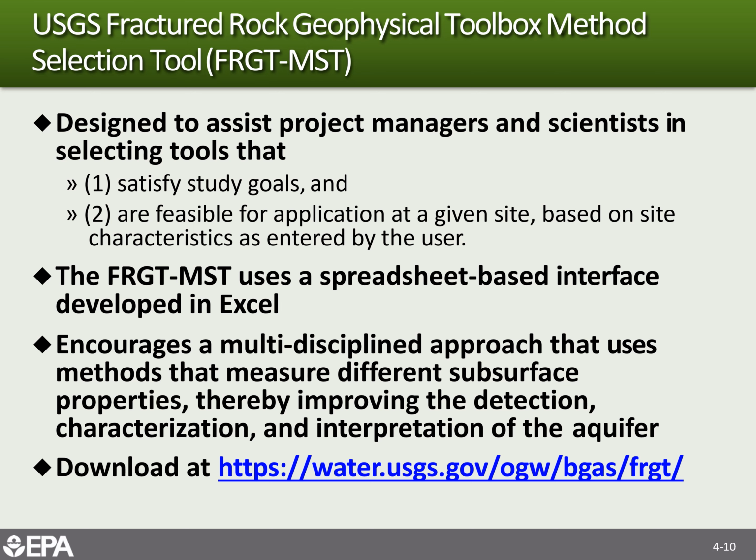They actually have a fractured rock toolbox, like the one from the ITRC, where you go in and look at it, and it will tell you the various tools and ideas to use when you're looking at, in this case, just fractured rock, but they also do field investigations. I've used them on sites in North Carolina to run geophysical logging in our fractured bedrock sites. Top quality, top-notch organization, and I recommend browsing their website.